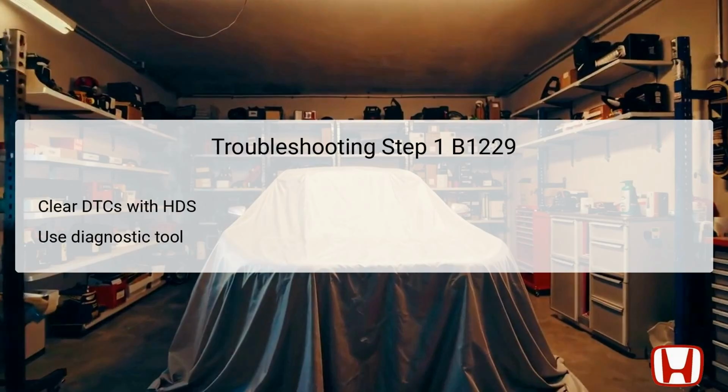The first troubleshooting step in diagnosing DTC B1229 involves clearing any existing diagnostic trouble codes, DTCs, using the Honda Diagnostic System, HDS. The HDS is a specialized diagnostic tool designed for Honda vehicles, which allows technicians to read and erase codes from the vehicle's onboard computer. Clearing the DTCs resets the system and aids in determining whether the fault is persistent or intermittent. This initial step sets the stage for subsequent diagnostics.